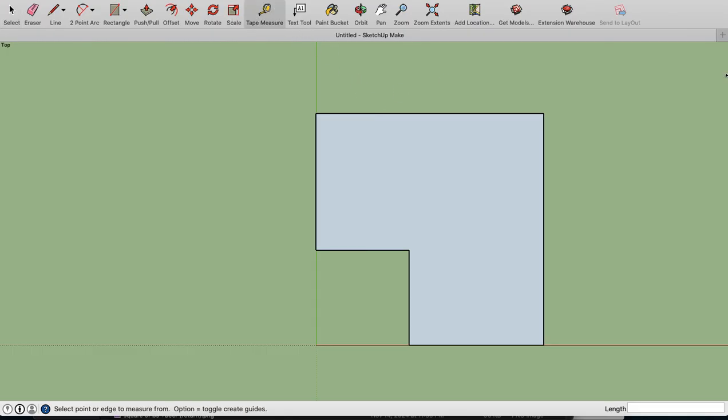And again, I use the same principle. We are trying to develop building dimensions based on an extending rectangle that is surrounding this. And so this one becomes pretty clear because we've got the axes here. So in this axis, the building dimension is still 40 feet, and in this dimension, it's 40 feet as well. So this building, although we've changed the footprint, would have the same amount of bracing that would be required, since it has the same building dimensions. Okay, so again, we can mix this up with a few different ideas.